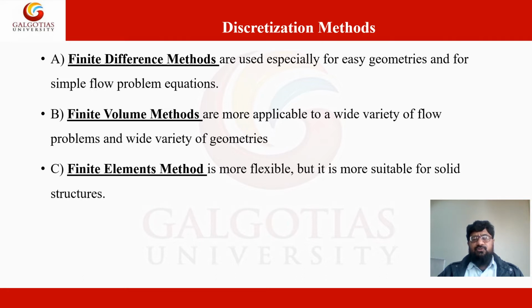However, it is more suitable for solid structures, because in fluid flow problems, a boundary layer forms and the finite element cells compress inside the boundary layer, because near the boundary layer we have to refine the mesh and cluster the cells. So we have to compress the finite element cells. Because of that, distortion can take place.